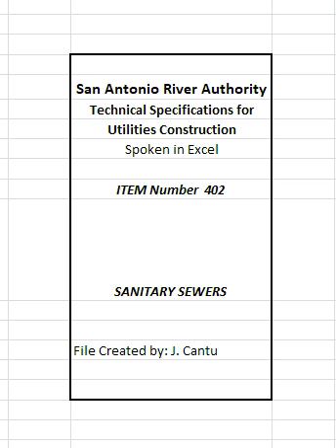4. Pipe laying. The field representative will inspect all pipe before it is placed in the trench and will reject any sections found to be damaged or defective to a degree that would affect the function of the pipe. Rejected pipe shall be immediately removed from the site of the work. The contractor shall be required to commence construction and laying of pipe at the downstream end of the sanitary sewer outfall line and proceed non-stop in a forward upstream direction unless otherwise noted on the plans.